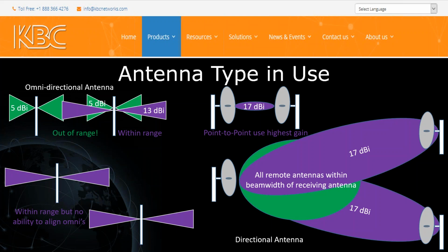So we can tell you what we feel comfortable with. For instance, we deal with directionals much more than omnis, so that's why I'm going to give this to you in directional as compared to the omni. But the directionals, if you had two of our highest gain directionals, the 17s, and you had wide open line of sight and you're up high on both ends, it's been tested at 5 miles. We've had people tell us success stories even further than that.